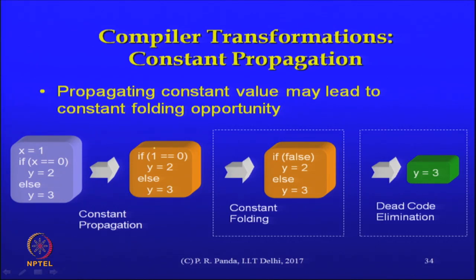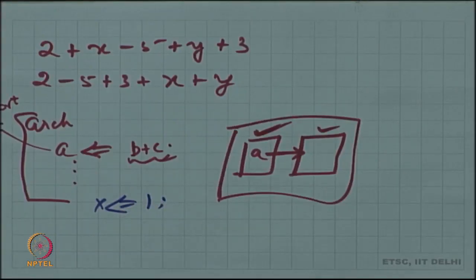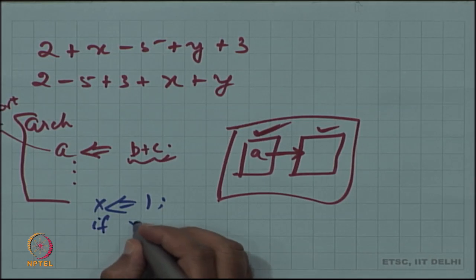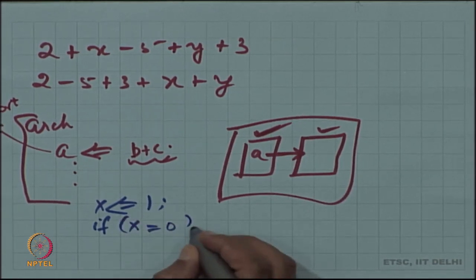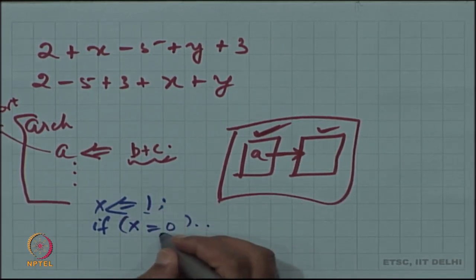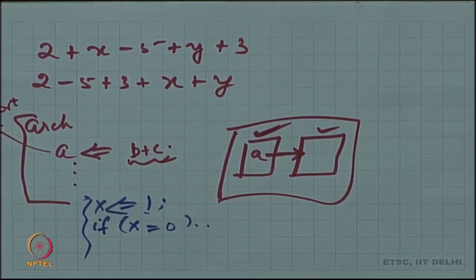Of course, through all this you remember that in the signal assignment, when you do x equals 1, it is not immediately visible in the same delta. Therefore, that new value, if this was a signal assignment, would not reach the x equals 0. Is that clear? If I had x equals 1, and immediately after, if x equals 2, so this is VHDL, then that new value does not reach this because we did not have an intervening wait or something like that. You have to wait until the next delta, and therefore, that does introduce some complication here.